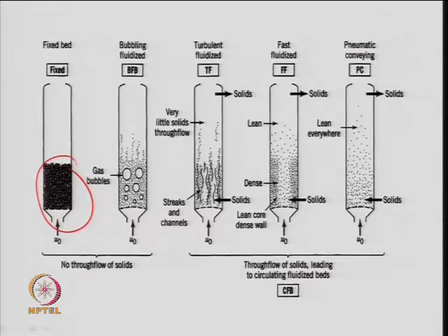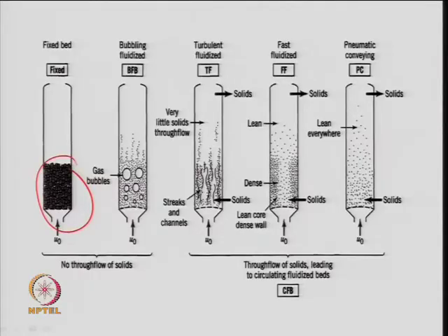But when you have a still higher velocity, you can have some throughflow of solids. So, that is more and more movement, and your voidage between the particles is increasing, so your pressure drop will be low now, right. The contact between gas and solid may be better, but there may be a situation where you have a slug flow condition, a pocket of solids and then gas leaves, and channeling may appear, right. That is a kind of turbulent fluidized bed.